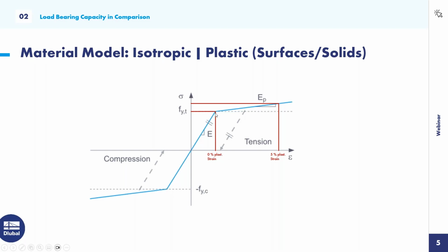But when you get a design ratio of 0% for the plate, then you are in the elastic area of the stress-strain diagram for the end plate, for example. It's a little bit tricky, but we can only compare the plastic strain. When you have a design ratio over 0, then you are in that area here.